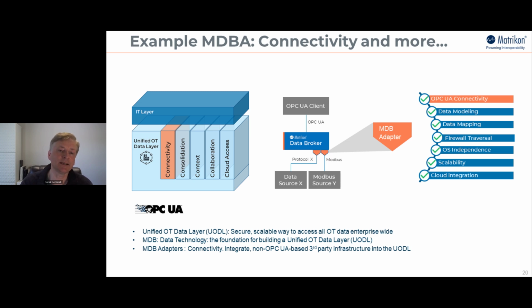But if you bring that in, where you talk the registers, but you bring it into a UA address space, now what happens is you can start grouping that information and putting some structure around it. And therefore, everybody who wants to get the information coming from that particular Modbus device no longer needs to even know Modbus, obviously, and doesn't have to work with the registers, because that maps into symbols or items, names, which they can address directly, and those can even be part of a structure, so you understand what the overall structure of whatever you're working with.